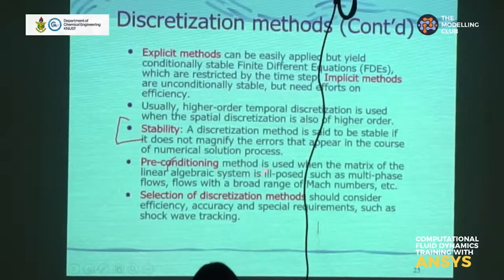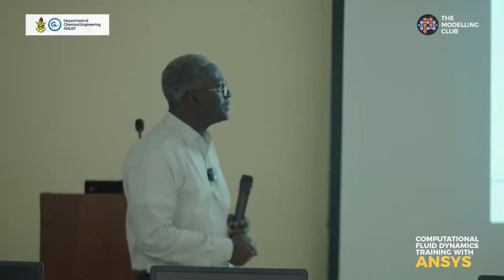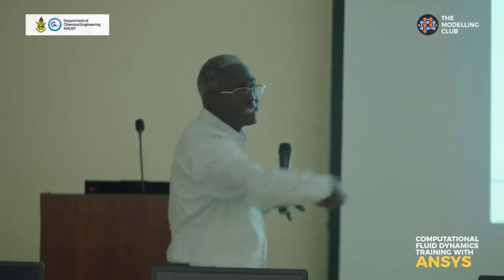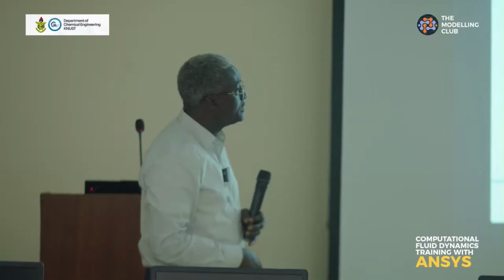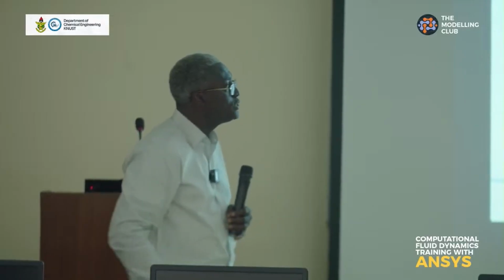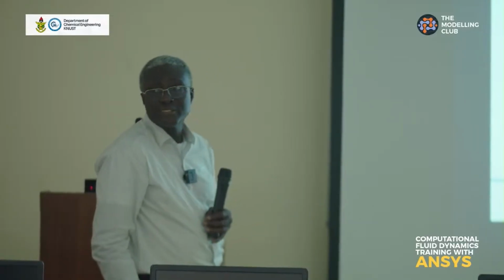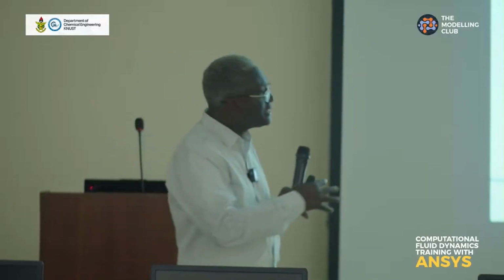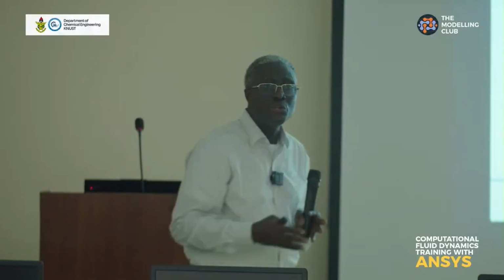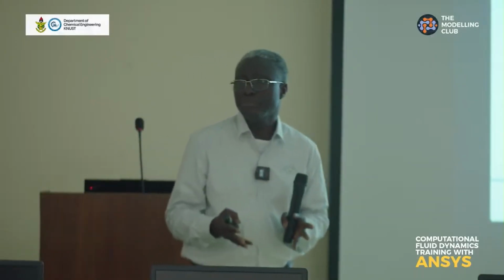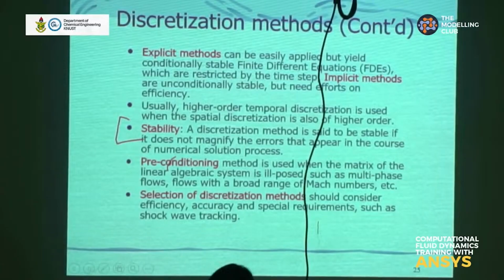Now, the preconditioning method is used when the matrix of the linear algebraic system is ill-posed, such as in multi-phase flows and flows with a broad range of Mach numbers. When you assemble your matrix for the discretized domain, you can end up with an ill-posed matrix. Some matrices are so nice, so beautiful, that you can use a standard algorithm, such as the Thomas algorithm, which is a tridiagonal matrix solver, to quickly solve the problem.